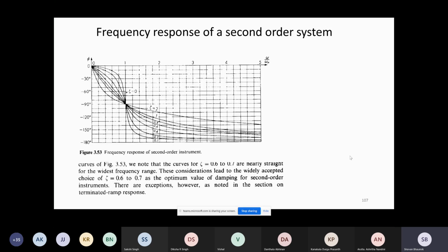The first approach is very simple. You take the transfer function and make an x column and a y column. In the x column, you keep putting different frequencies in radian per second. For example, you can start with 0.001 and gradually go to 10 to the power 6. So you write many frequencies in the omega column. In another column, which is the gain column, you calculate.